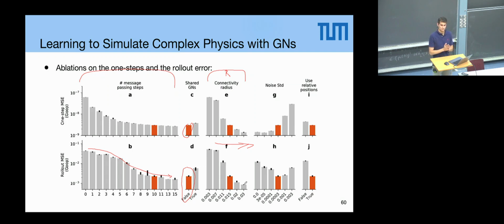You mean fixed times? The size of the time step. Yeah, okay. Yeah, the time step size is kept fixed. So in numerical simulations, we need a very small time step to guarantee numerical stability. Here we can use a larger time step because we don't have those problems. If you use a very large time step, then we are going to get very bad results, but it's also going to be faster. So the only option is to pick some of those time step sizes and see which one in the end has the highest accuracy at the end of the simulation.